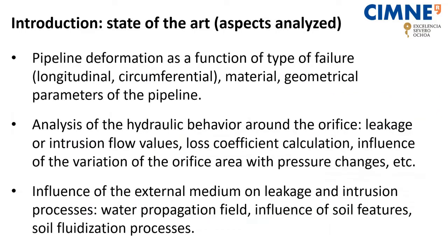What kind of features are studied in technical and scientific literature related to this topic? Well, some studies are focused on the structural behavior of the pipe, calculating the deformation and stresses depending on different parameters, type of failure, the material, or the geometry of the pipe. Other studies analyze the hydraulics around the orifice to calculate the leakage or intrusion flows and velocities, the discharge coefficient parameter, and other topics related to computational fluid dynamics.